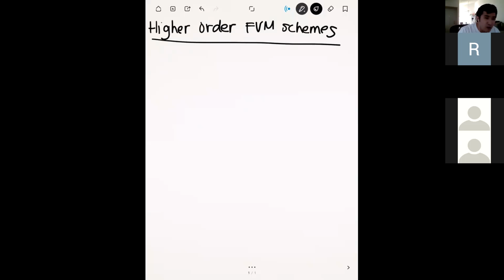So to kind of start, let me write out one of the surface integrals that we did, or the face integrals, right? Because remember, when we're doing finite volume methods for problems with convection diffusion, at least in 2D, the goal is to evaluate those four integrals: the east integral, the north, the south, and the west. Okay? So let me write out one of those again.